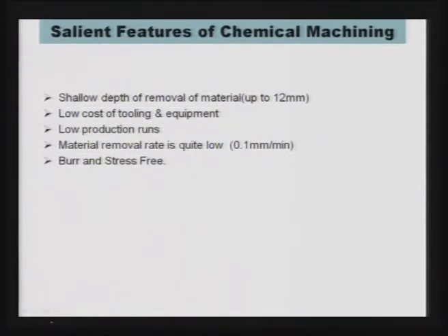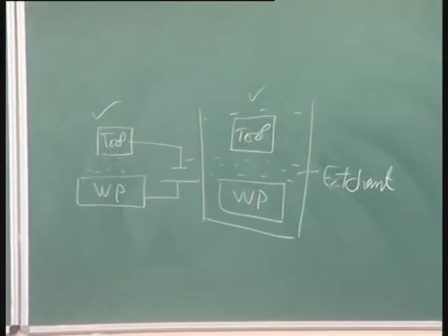Work is stress free, and removal of the material is burr free, as you can clearly see in chemical machining. There is no mechanical force, no thermal energy, it is only chemical reaction which is removing the material, hence it is burr free, and there are no thermal or mechanical stresses on the machined component.